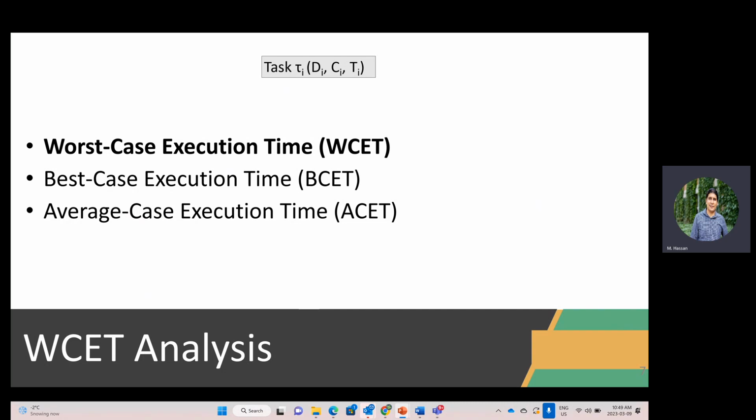So in the same system, you have a hard deadline, a hard real-time task, we call it hard real-time, which is of highest criticality, engine control, airbag, cruise control might be. And then we have also infotainment unit, GPS, reporting or logging tasks. All of these are kind of average case. And they care about average case performance. And the challenge is you need to accommodate for both.